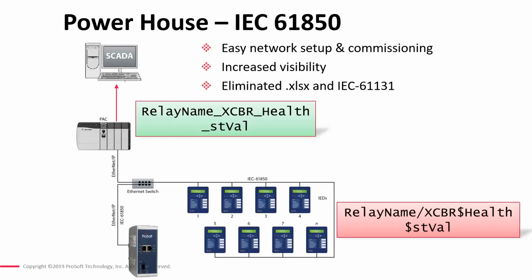There was a question that came in regarding multi-master access to IEC 61850 devices. I just wanted to touch on that really quickly. A lot of times there's quite a bit that you have to do for multi-master. One of the things you have to do is make sure that you have a slave device or a server device that actually supports it.